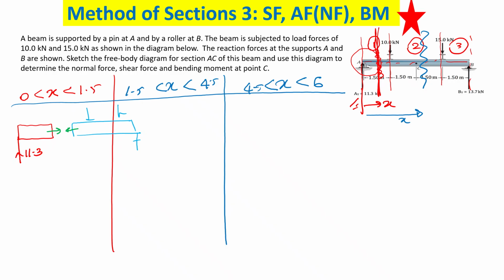And the shear force. Shear force is always turning this in the clockwise direction. So this one is turning clockwise. Do you see that? And this one is turning in the clockwise direction as well. So this is a sign convention. So you have shear force like that. Makes sense? And also you have the bending moment. Bending moment is always put in this direction.